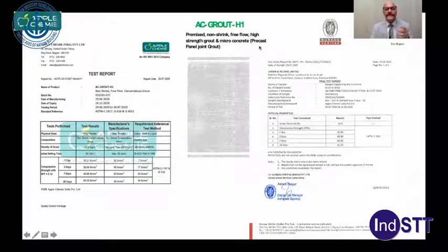See, there will be manufacturers. This is one of the best manufacturers. Yes, they have said that it will be pre-mix, non-shrink, free flow, high strength panel grout or joint grout, and there will be a test certificate or a manufacturer test certificate.